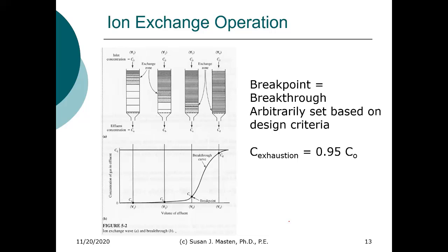The ion exchange system operates the same way as your adsorption system. In fact, this is the exact same figure that I used for adsorption. With adsorption, we talked about an adsorption zone. With ion exchange, we talk about an exchange zone, exactly identical. If this is our exchange zone, at the bottom of that exchange zone, this concentration is the exhaust concentration.